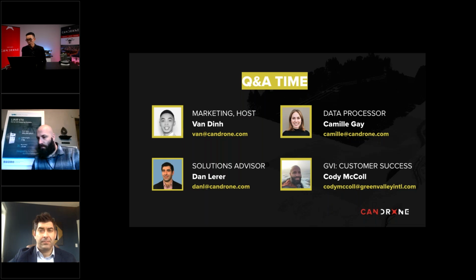The first question we have from Eddie: LiDAR takes a lot less processing power than photogrammetry. Would you agree with that? Yes, that is very true. I don't know exactly the ratio, but the LiDAR processing is way faster. It's mainly because each point in LiDAR data is already a three-dimensional XYZ point. With photogrammetry, if you want to make a 3D model, you have to turn 2D images into a 3D model, and taking an XY and having enough processing power to make it into an XYZ is infinitely more processing intensive. So you're right on with that, it's going to take a lot more processing to do photogrammetry 3D models.